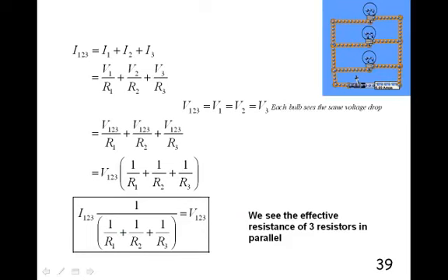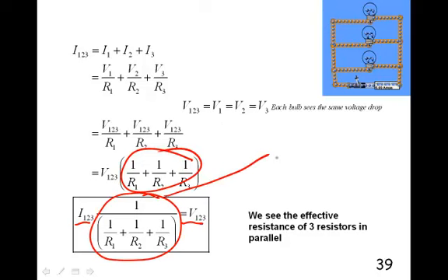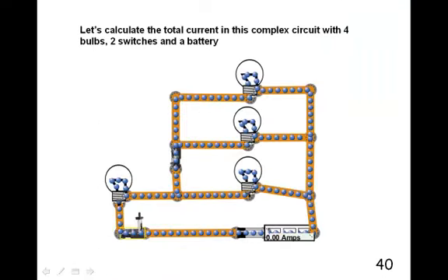Alright, but what's important about this derivation right here is I can divide both sides by that quantity, and I end up with V equals I times, this is the equivalent resistance. So that's the equivalent resistance of a parallel combination of resistors. Better write that down in your notes. It's the opposite of how capacitors work. Well, let's jump to a little more difficult problem.